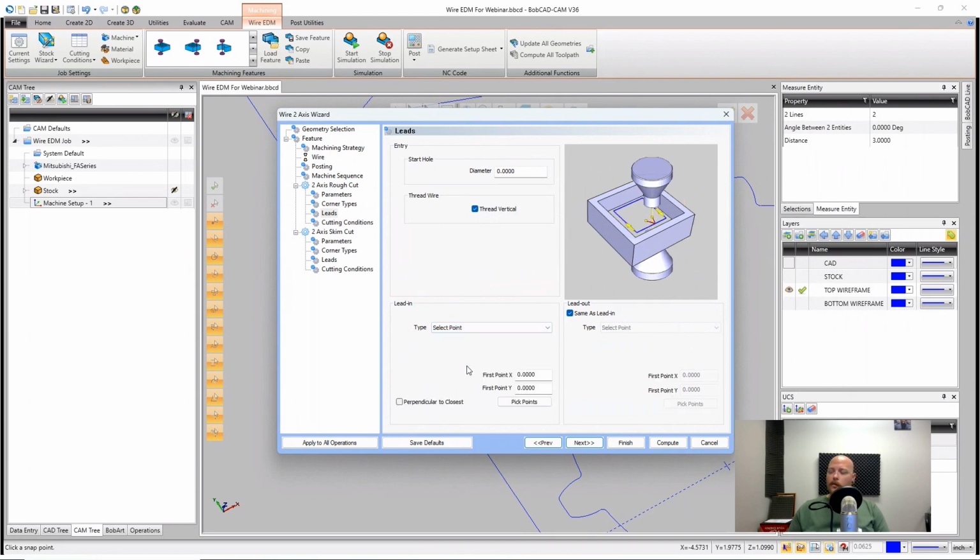And this is the one we're going to use where we have to make sure our wire feeds through a specific location. The way we do that is we pick the points. I should be able to pick the points inside the arcs that I have on my stock layer to pick them, to get the origin for it.